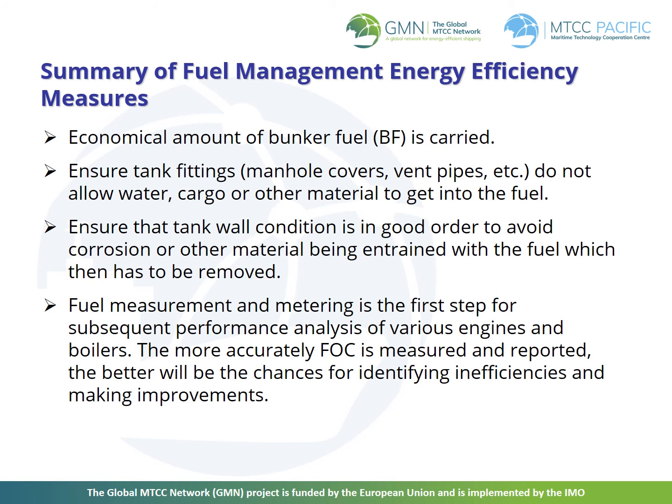An economical amount of bunker fuel should be carried. Energy is also used for temperature control of fuel and its transfer. To ensure energy efficient storage and transfer, fuel temperature in storage tanks needs to be controlled to the lowest feasible temperature in order to retain it in a fluid condition and also render it suitable for transfer.